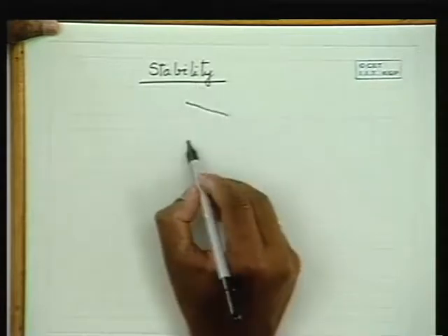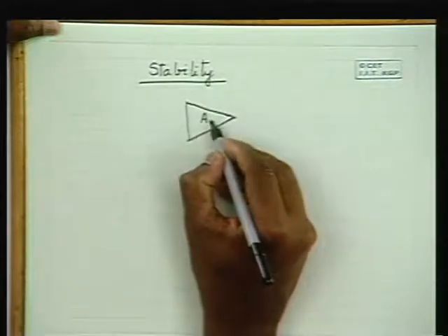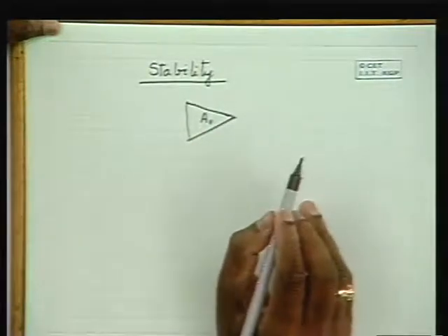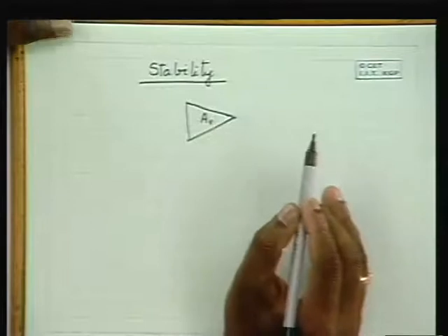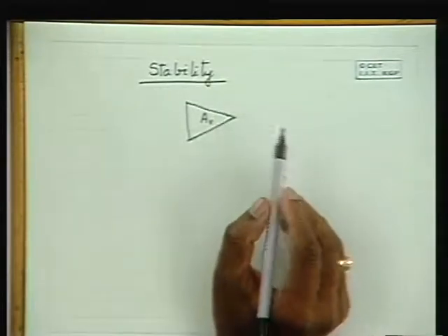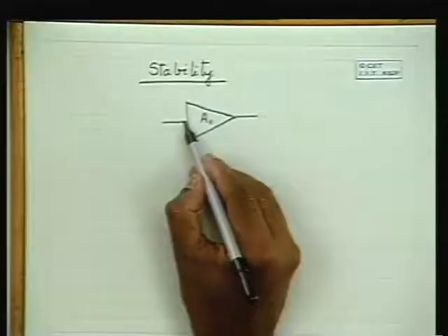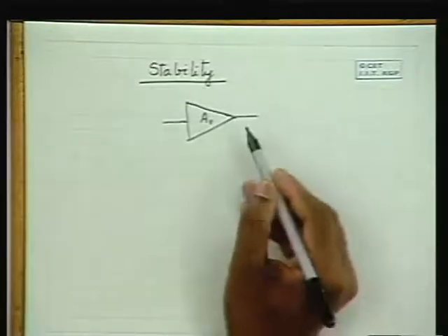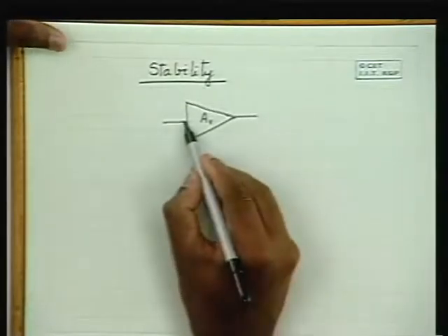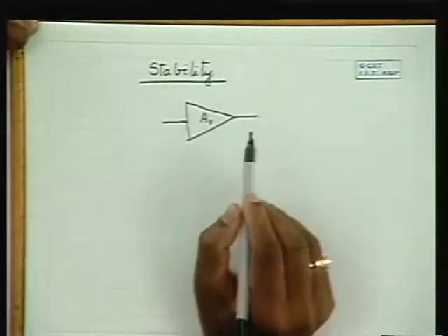If we have an amplifier and the amplifier has parameters like the voltage gain, input impedance and output impedance and so on, say this parameter, the voltage gain, varies for some reason, due to either temperature variation or replacing a transistor amplifier by another amplifier. So the amplifier characteristics change, namely the gain changes in this particular example. Now with feedback, the effect of the changes is very small.